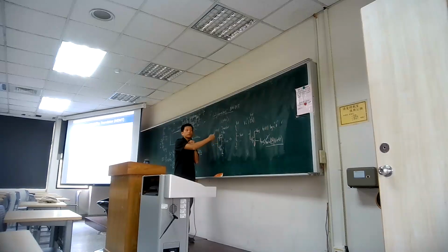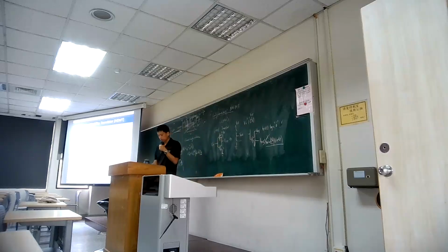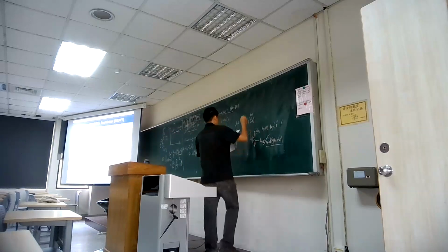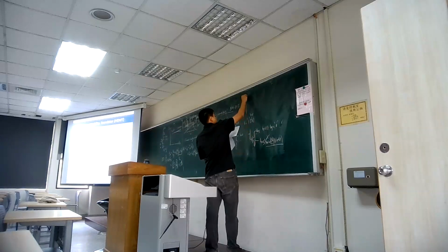And vice versa, if you get a 0 voltage here, that means you turn off the NMOS and you turn on the PMOS. When the PMOS is on, there will be current flow, and then you get the voltage like VDD minus VT, just like a VDD to be here. And then you get a high voltage response.